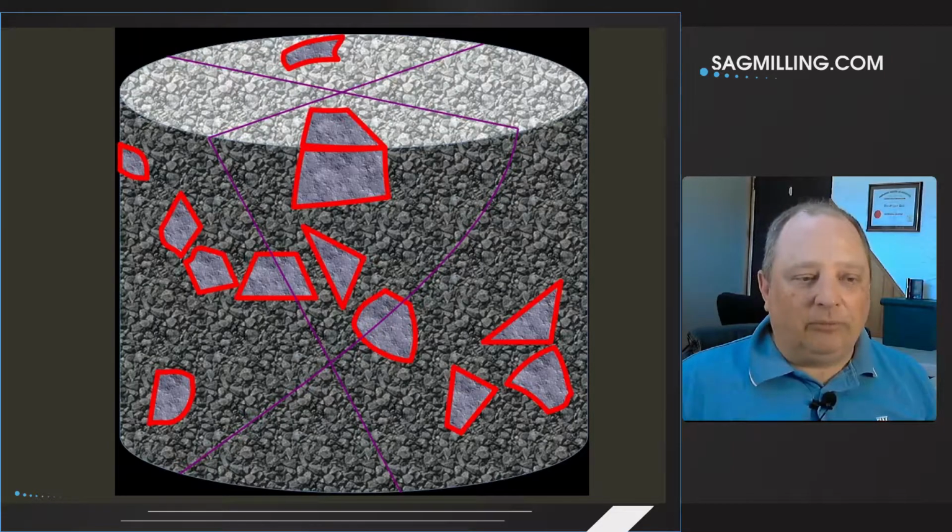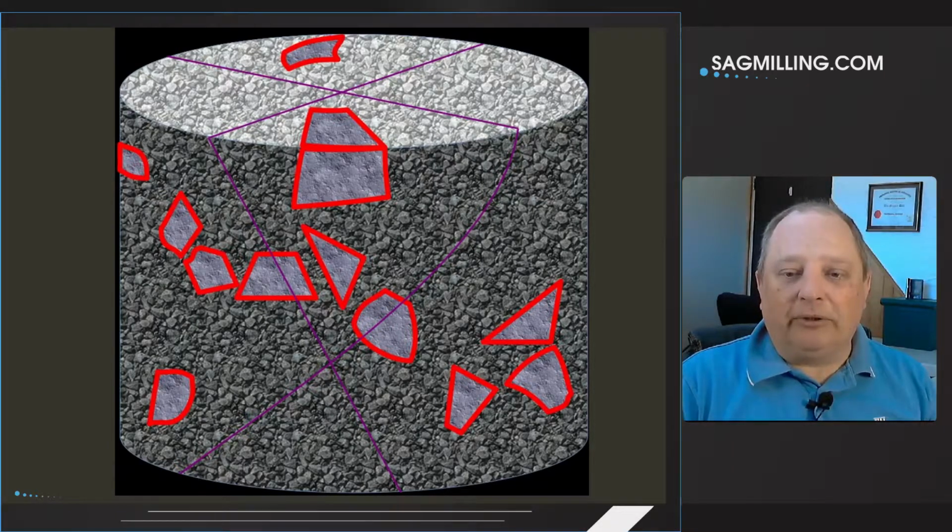We've got some coarse brecciated particles, which the individual clasts that you're looking at here, they might be softer than the ground mass, they might be harder than the ground mass, but they're probably going to have a slightly different grindability characteristic to the overall rock, especially along these boundaries. You might get a preferential breakage right around these boundaries.